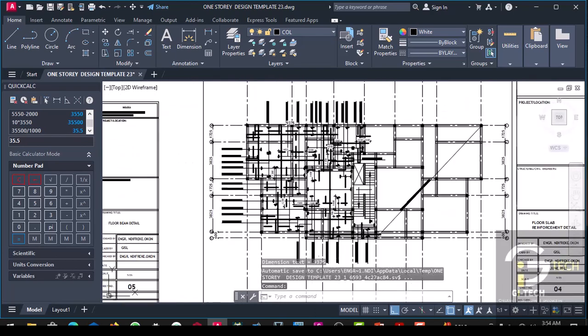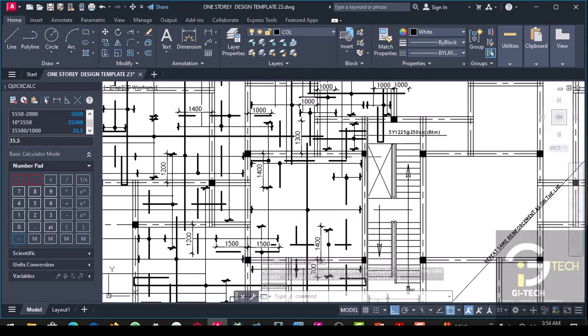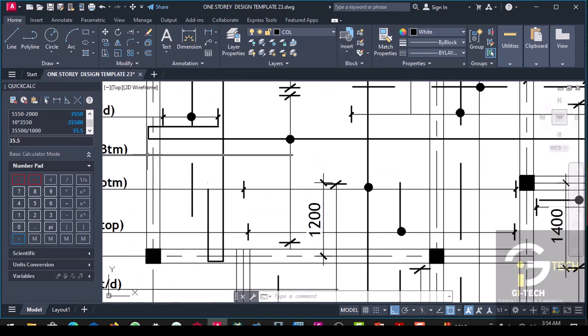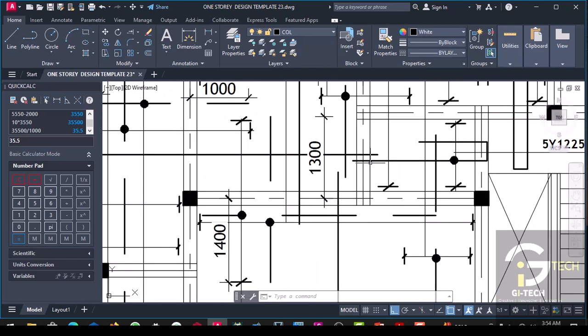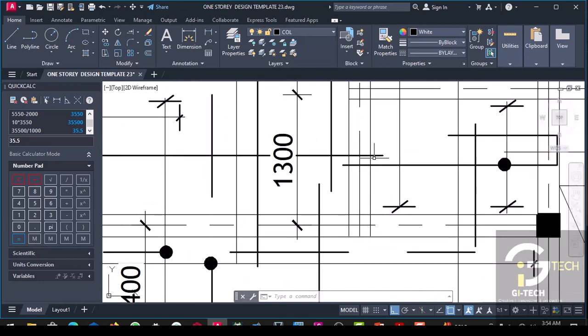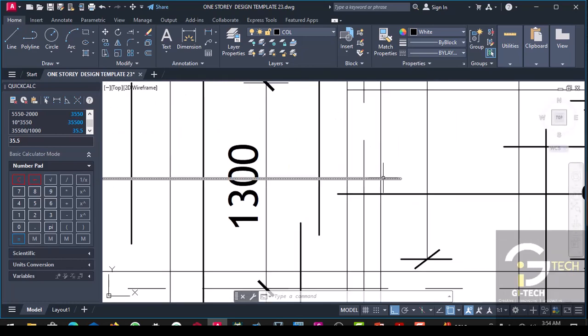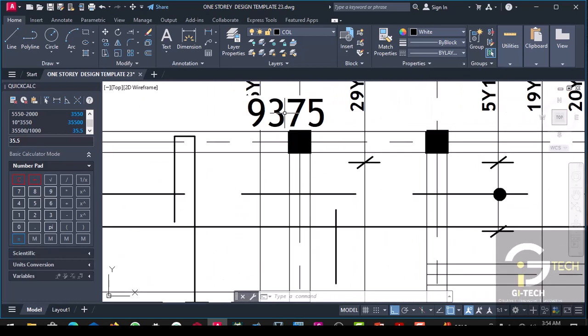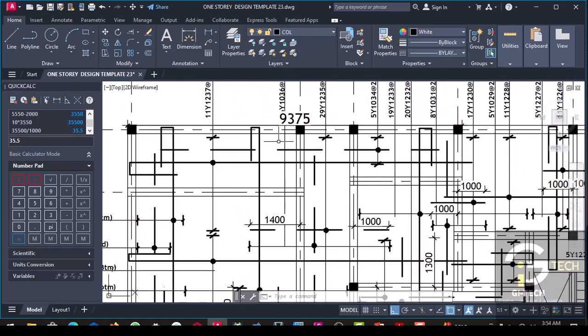Now this 9375 is out to out. So we assume that from here we must have a projection of 300 so that it can overlap properly with this one. So we also project this 300, so that by the time you join the two, you can tie them. We will add that 300 to 9375.